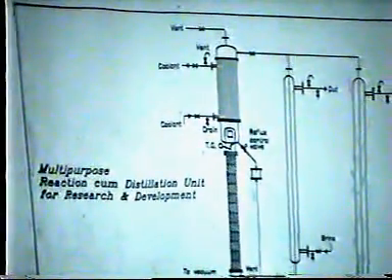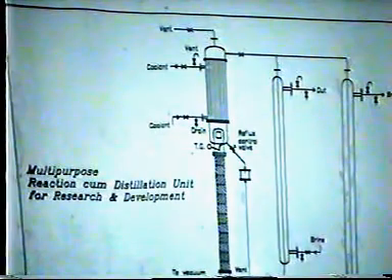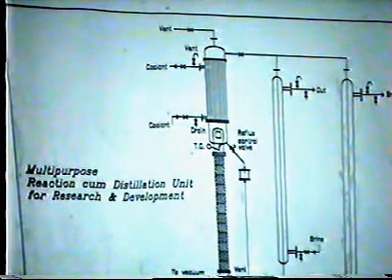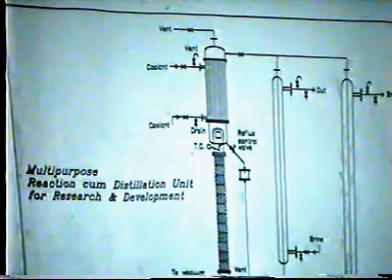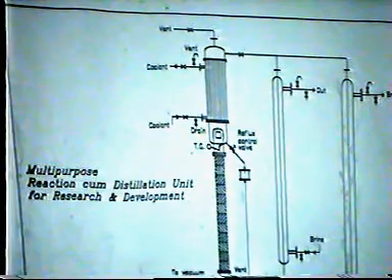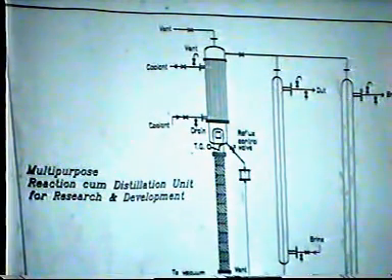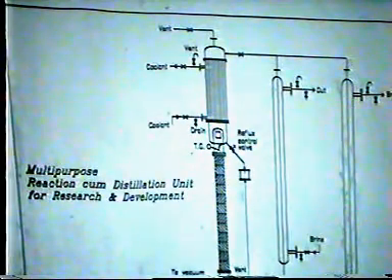Subcooler, which accomplishes subcooling of the distillate. Below this vapor head, we have a subcooler here, which subcools the hot material which is coming out as condensate. A primary receiver to collect the distillate is below that subcooler, and a secondary receiver to collect and withdraw the distillate is below that.